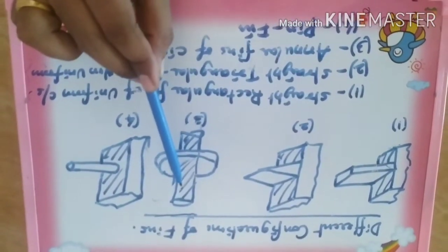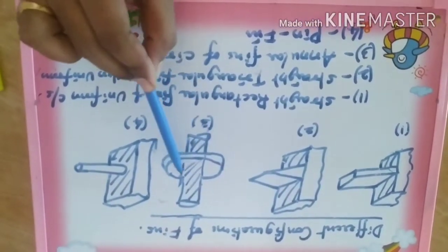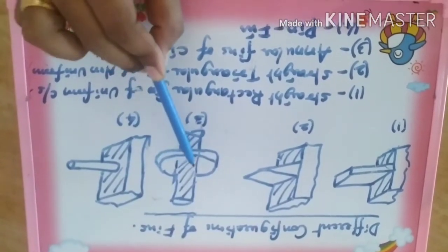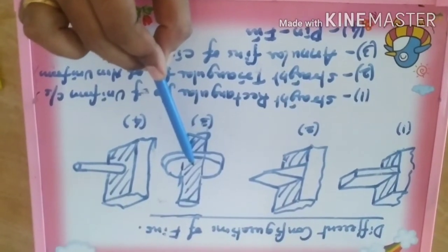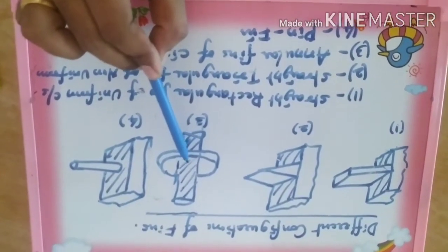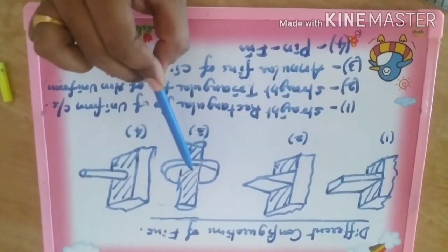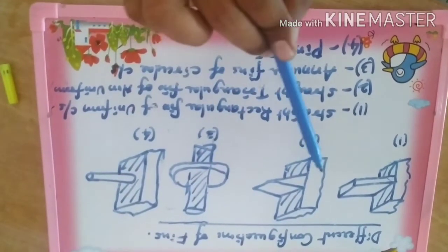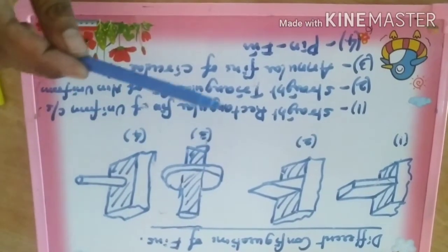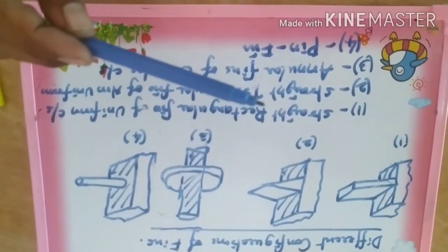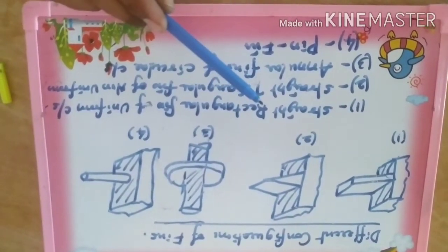I repeat again, the base surface is of cylindrical form, and surrounding that base surface we are attaching circular cross section fins. Sometimes they are also referred to as annular fins. These kinds of fins we in general find in the applications of steam pipes. Surrounding the steam pipe, we can attach the fins annularly or circumferentially over the pipes, so as to increase or decrease the heat transfer.